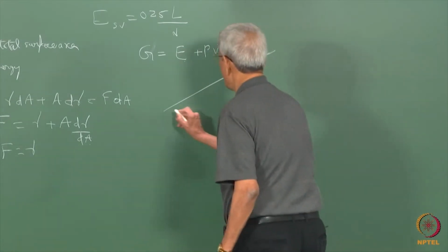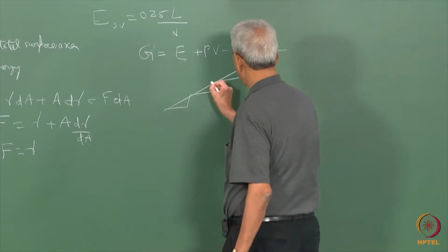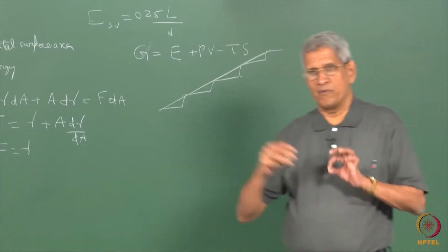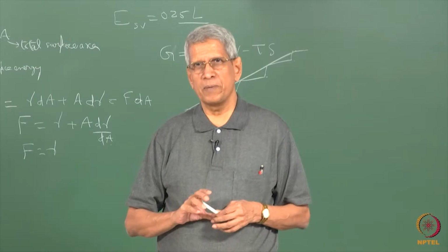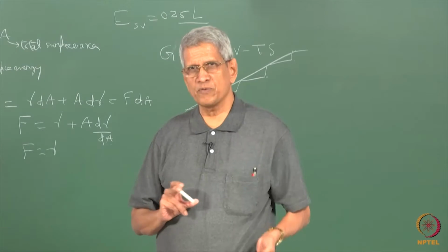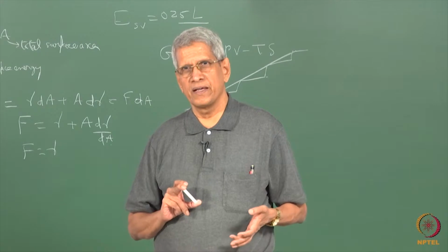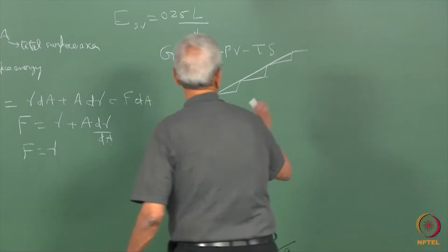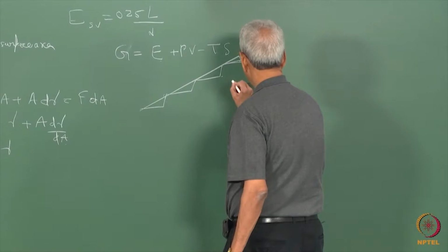So, with steps, if we try to create a surface like this, if you look at each of these surfaces, this will be a low index, only some step is being created. That means that closer to a step, the number of bonds which are broken will be slightly different. Using this number of broken bonds, we can try to calculate the surface energy in terms of the close packed plane. With respect to this surface, what is the angle theta?